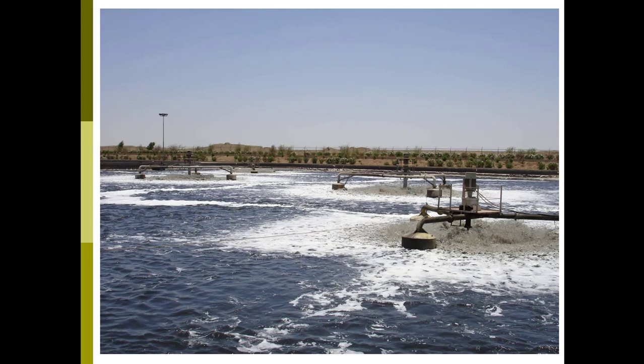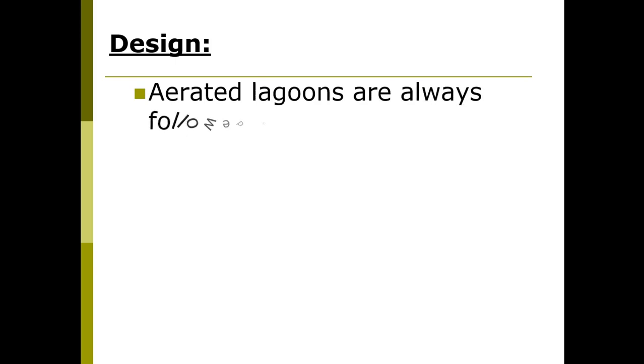Regarding the diffusers, they can be arranged similar to the activated sludge systems. However, normally in the aerated lagoons, as you can see, it is a very wide area, so normally we use surface floating aerators. Okay, now let's go to the design equations.